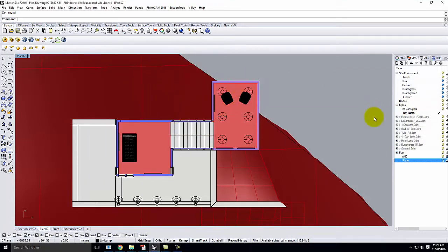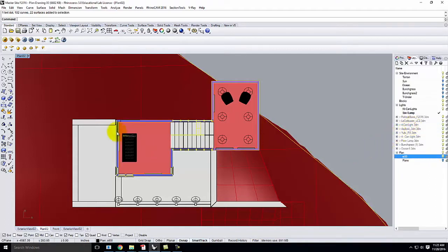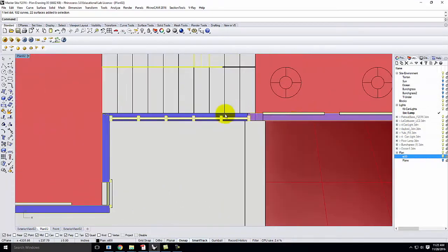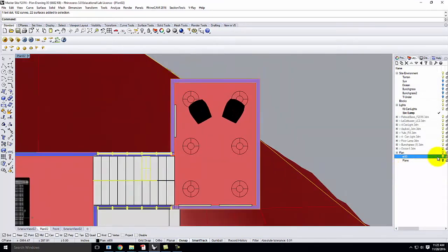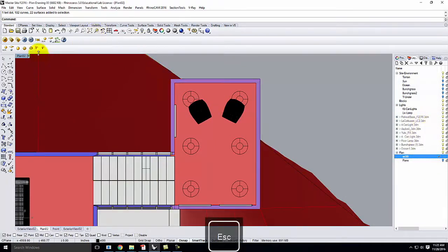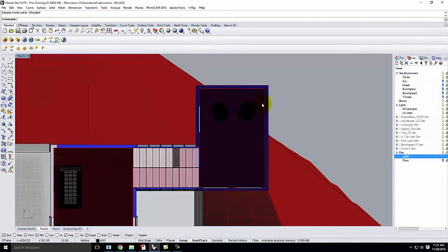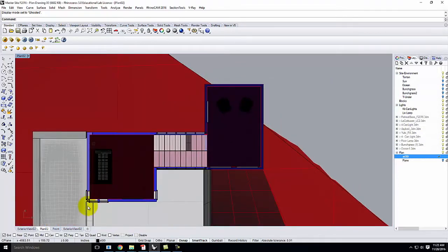OK, so let's take a look at what is on the ST00 layer. Let me unlock it, and let me select the objects that are on that layer. Okay, it gave me a bunch of curves, but not too much else. So I'm going to have to do some cleanup and essentially filling in of what I've cut through. All right, and let me go ahead and view this in ghosted mode for just a second so we can see. All right, so I'm going to have to fill in a little bit.